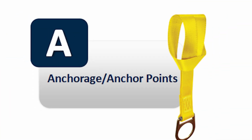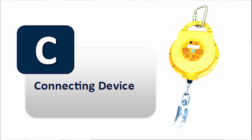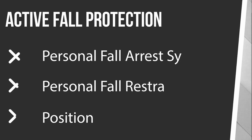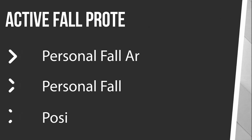When talking about active fall protection systems, it is important to remember the ABCs of fall protection. A is anchorage, B is body protection or a harness, C is connector or a lanyard. There are 3 types of active fall protection systems. They include a personal fall arrest system, personal fall restraint system, and positioning devices.